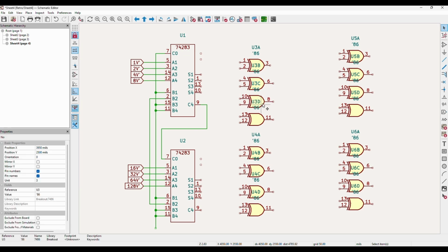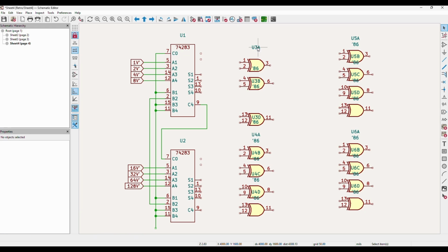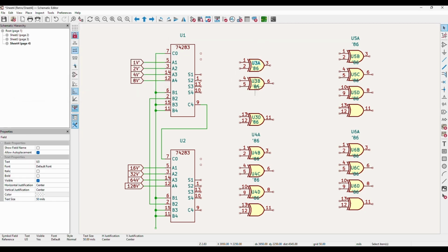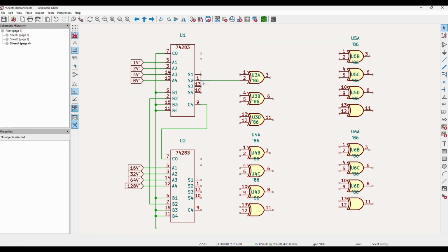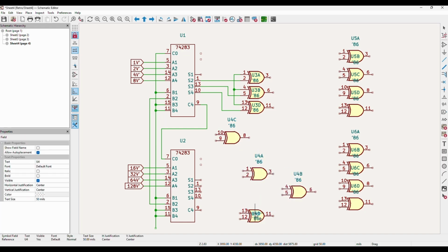They're using that fourth 7486 gate somewhere else, which is a shame because we could have added jumpers to completely bypass these 6 chips if you didn't need cocktail model support. The 7486s are cheap, so perhaps we'll just add jumpers to bypass the adders. Don't know yet. Still making this up as I go.